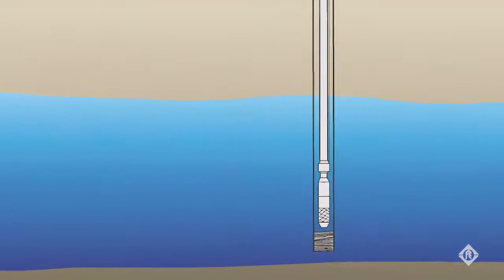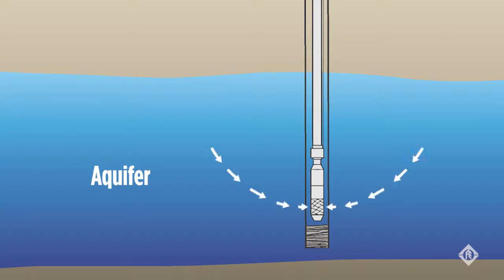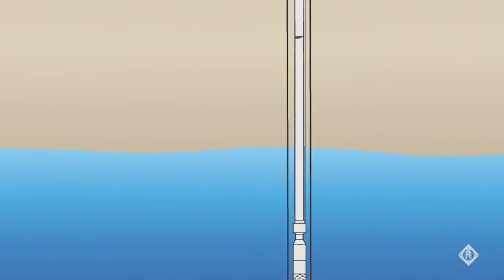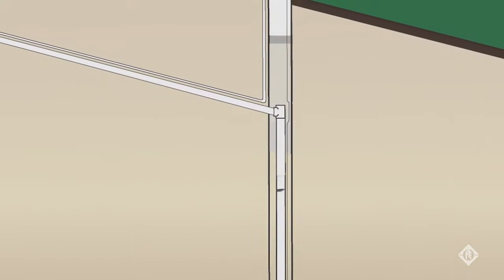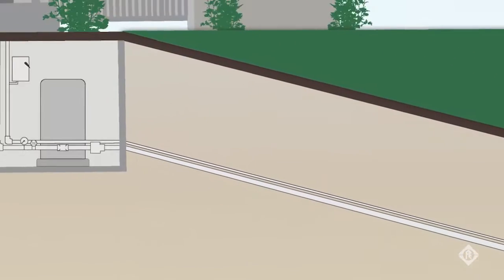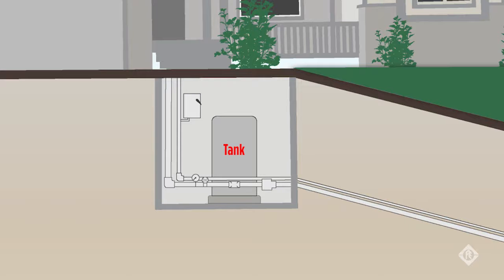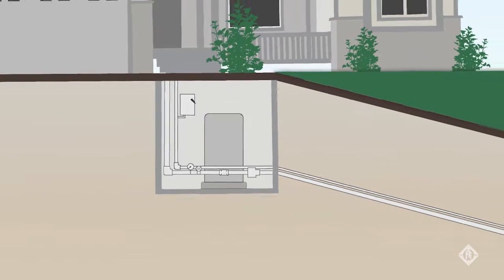4. Well capacity is how fast water flows into the well from the aquifer. A well of 3 gallons per minute capacity can easily be drawn down if we're pumping at a rate of 10 gallons per minute. If you pump at a rate of 3 gallons per minute, you can pump 1,800 gallons in a 10-hour period. In a case such as this, we usually put in a low flow pump and pump into a tank, or if we have a well of adequate depth and static level, the well can act as a reservoir.